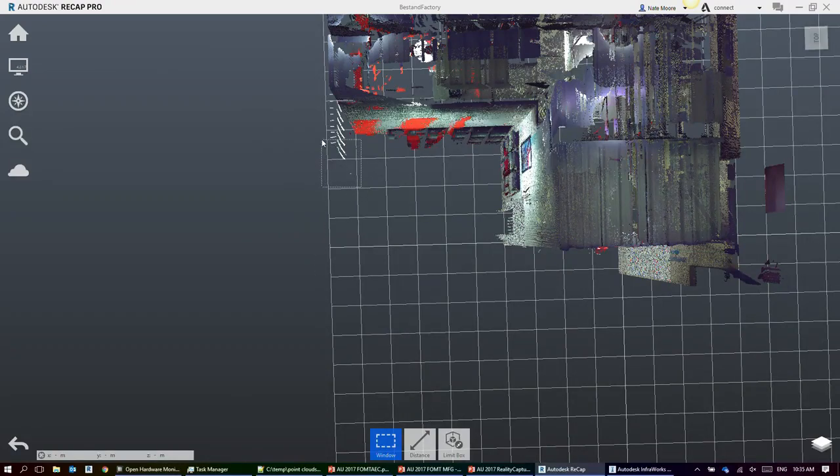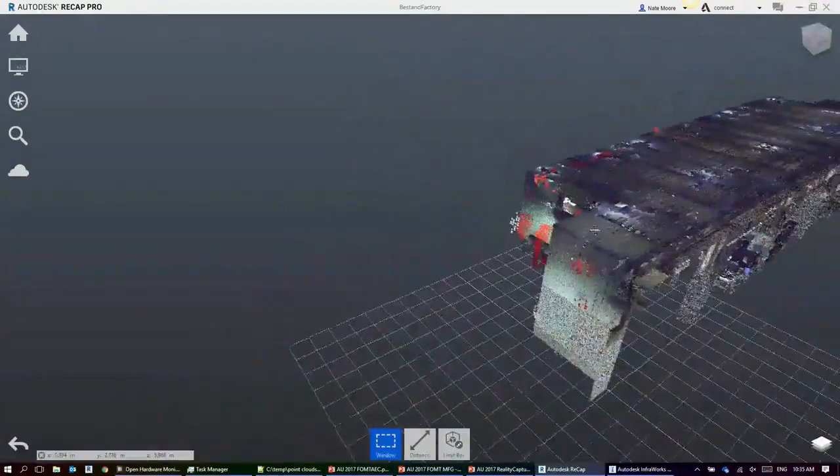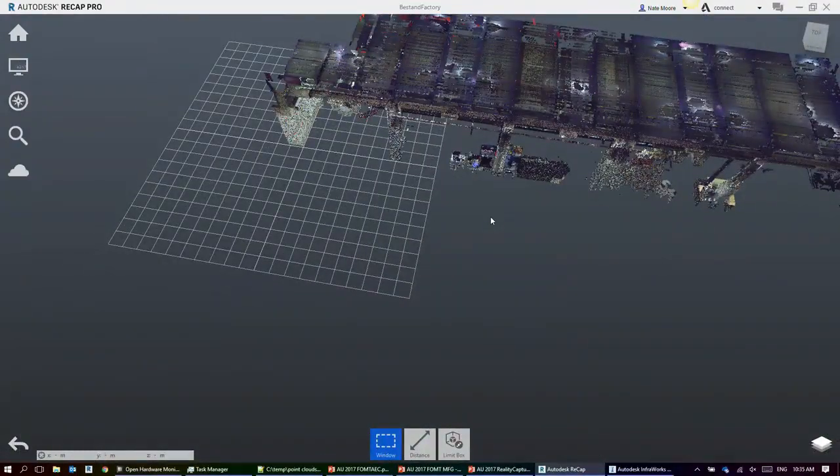So it's super simple. Just play with it for a couple of minutes, and you'll understand how it all comes together. So you can see that it's a region I've got turned off, and so by assigning that selection to it, it instantly goes out of my field of view, so you know what you're dealing with. So that's one way. If you want to be a bit more precise about things, particularly for me on the vertical, it's really nice to get the roof out of there, because you're always going to pick up ceilings and things like that, floors that maybe you don't really care about in the scope of your project.